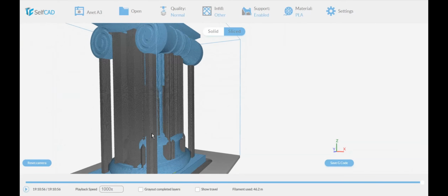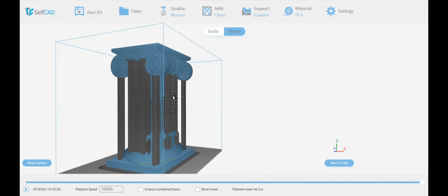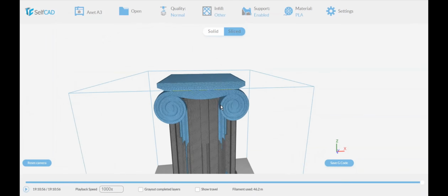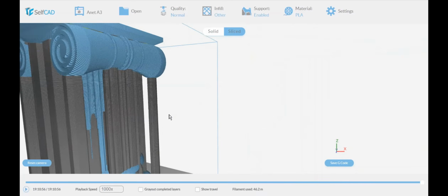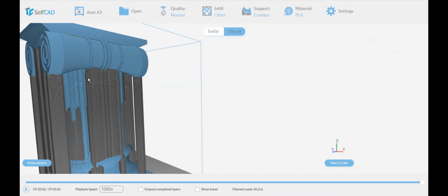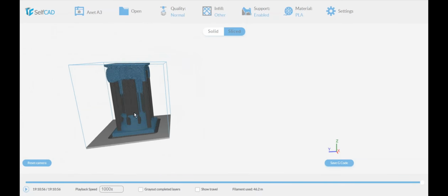It adds it in a logical section. Actually, you can see in the 4 corners you have a strong support to underline here, which is a big overhang, because this overhang is too far away from the base, so it definitely needs the support. But over here it needs it only a little bit here, and then it doesn't need it. So it's quite logical that it knows how to handle this type of stuff.